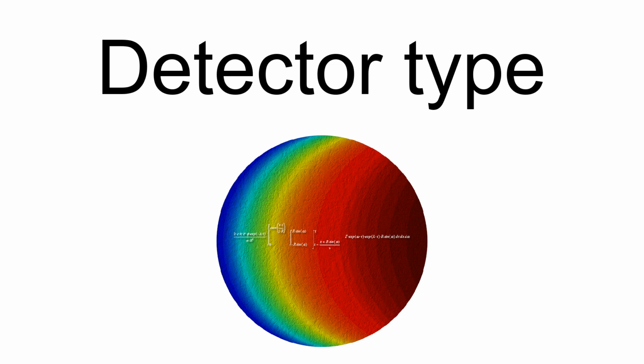In those cases, the interference from other isotopes such as radon is a major problem, and more sophisticated analysis, such as the use of HPGe detectors and multi-channel analyzers, is used where spectral information, such as is used for radon compensation, is required. Radioiodine, especially 131I, monitoring is often done using a particulate monitor setup, but with an activated charcoal collection medium, which can absorb some iodine vapors as well as particulate forms. Single-channel spectroscopy is usually specified for iodine monitors.